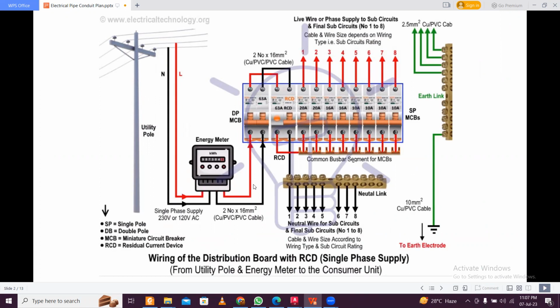So first of all, you have the main line from which the wires come, and we have an energy meter, and you often also have a main switch before the energy meter, and after this energy meter it comes to the MCB. So the MCB has connections to various parts, and these can be either a normal junction or a junction with a fan loop. From that, the wires go to various devices and switchboards, and from that we get electricity in our houses.